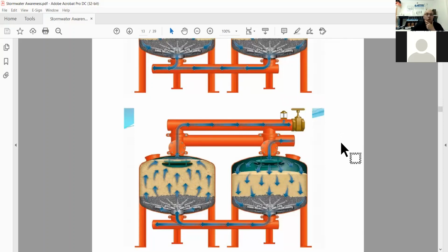So when you do this, with ATS systems, active treatment systems, certain California Regional Water Board requirements must be met before discharge, including discharge turbidity requirements, 10 NTU and 20 NTU, pH requirements, right now 6.5 to 8.5, automatic logging of water quality parameters, training requirements, chemical residual requirements.